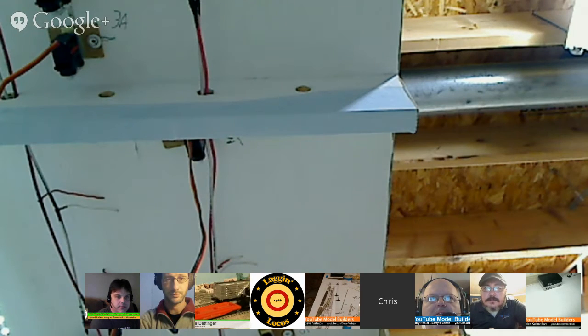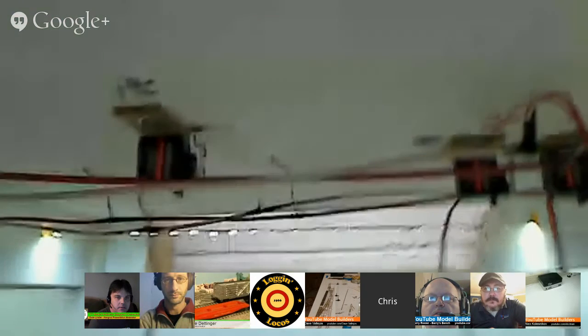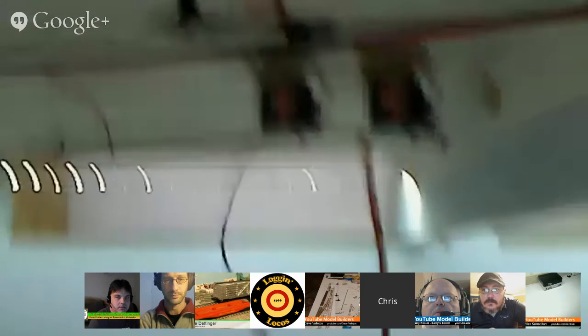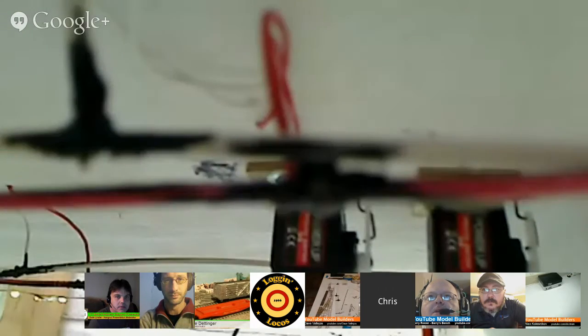Like I said, I bought standard 3-color servo bulk wire, pins and connector bodies, and a crimper, and did all my own harnesses. It looks like Chris is going to show us a little bit of what he's done. Oh, that's them. Nice. He's done his own brackets, and that's what the harness wiring looks like. Nice and simple. He even made his own homemade brackets there. Very nice.